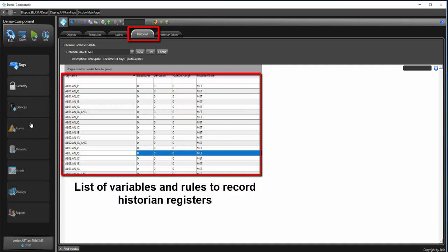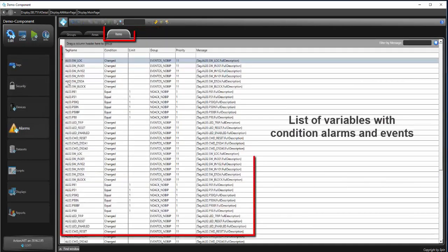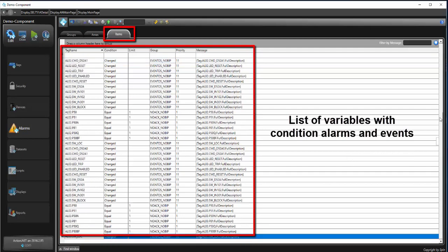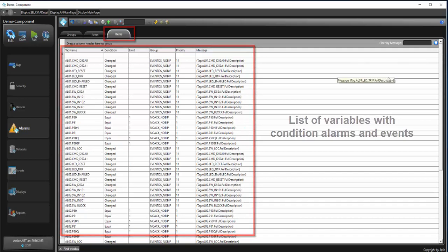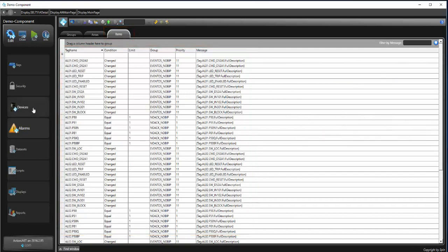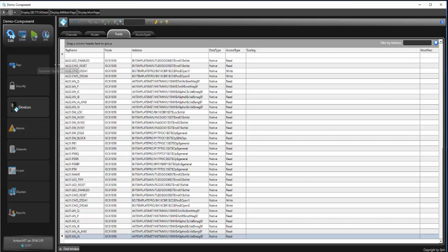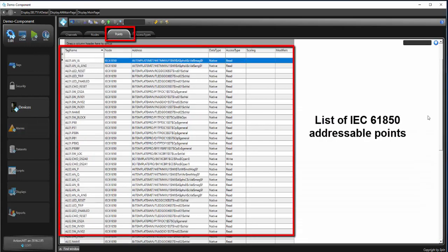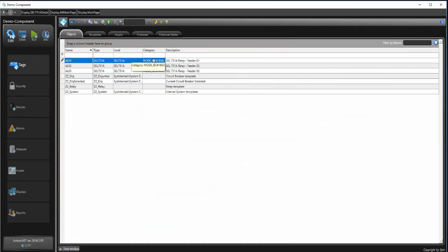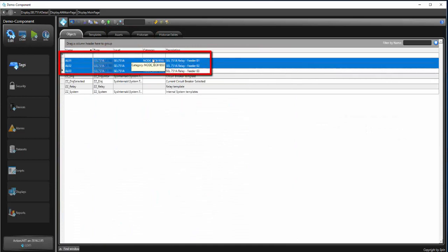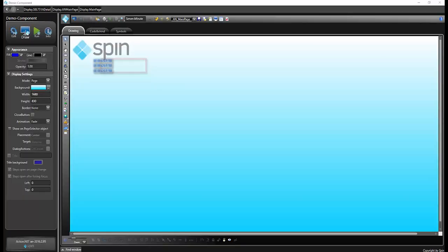After the execution, we verified that the 3 lists were correctly filled. To create the layout of the 3 feeders, on the Start screen, we will copy them from the Tags Objects screen and paste them into the Project Initial screen.